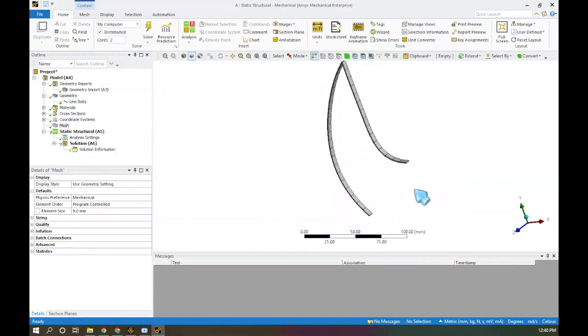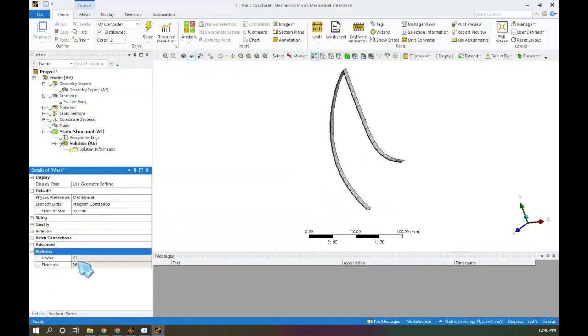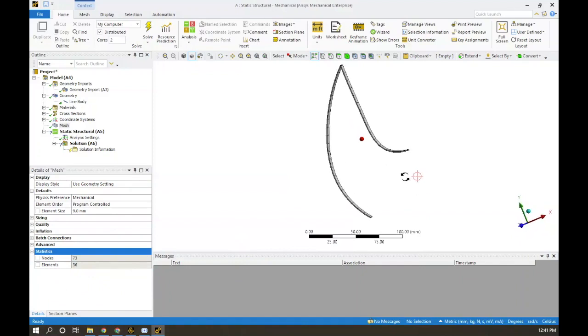If you want to look into the details of the mesh elements and the total number of nodes, you can click on the statistics, and they will detail out the total number of elements and nodes of the newly defined mesh. Just in case your mesh does not show this 3D view as in my display, then you have to activate the thick shells and beams function.